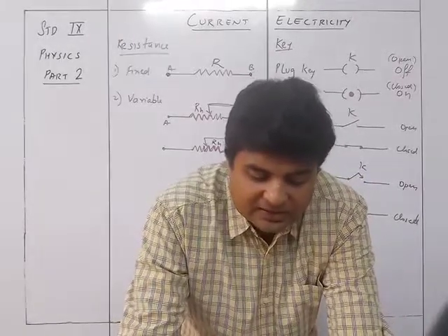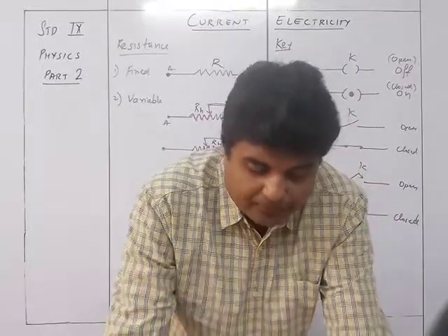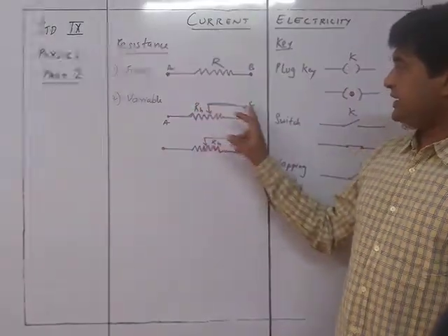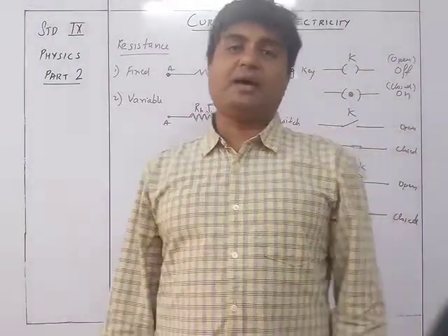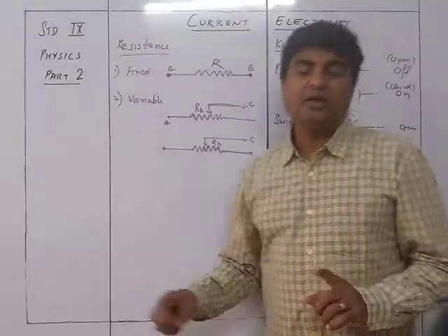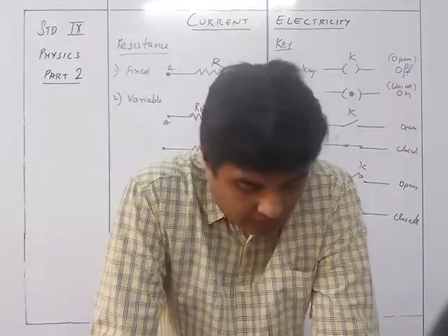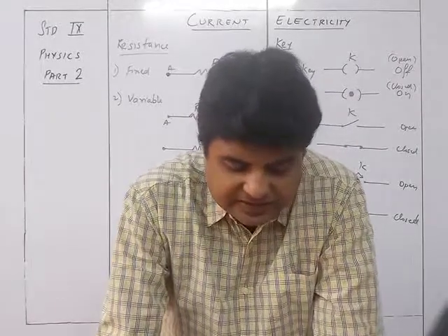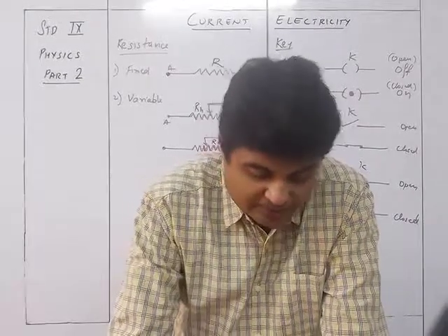The current then enters at the positive terminal A or B. It flows in the resistance wire of the length up to the jockey and then leaves at the terminal C. So that's why it will be either AC as the resistance or BC as the resistance. So accordingly, depending upon where the rheostat's jockey is placed and depending upon where the A connection or B connection is made to the circuit, it will give you a variable resistance. The rheostat provides a continuously varying circuit resistance to adjust current to a desired value in the circuit. Symbol RH is used for the variable resistance.